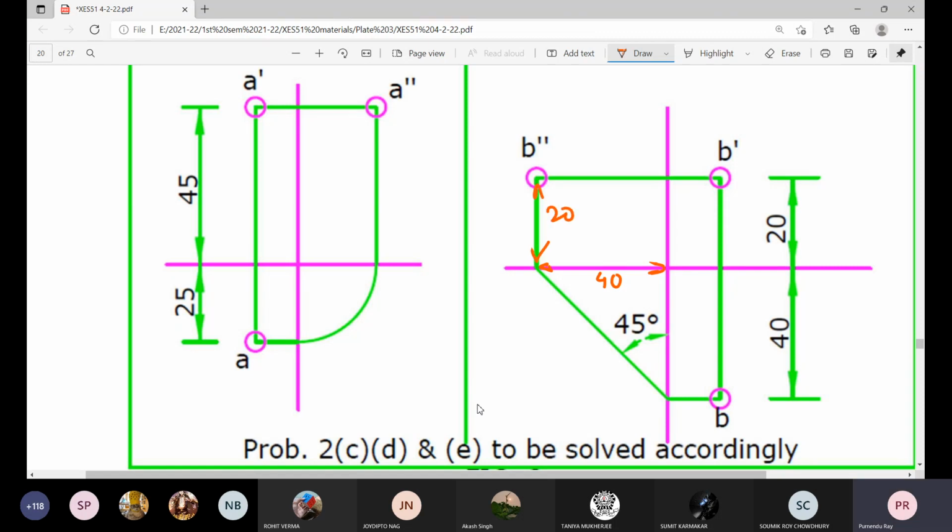That's fine, but we are not calculating. Simply we are using the geometrical tools to locate it here. It's not like along this line you measure a length of 40 millimeter, definitely not. And we are using this method of 45-degree line. Only this thing is shifted towards the left. When you are looking from right, you project on the PP placed on the left and open that space.